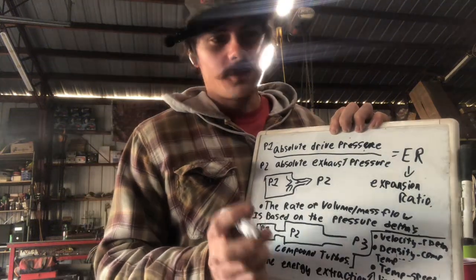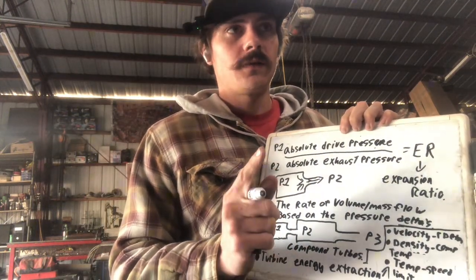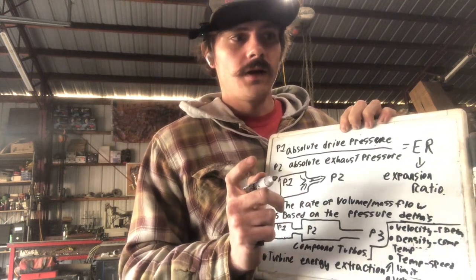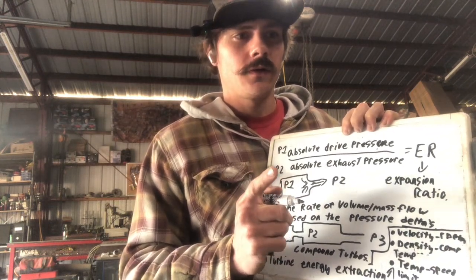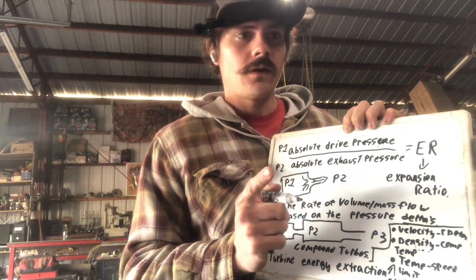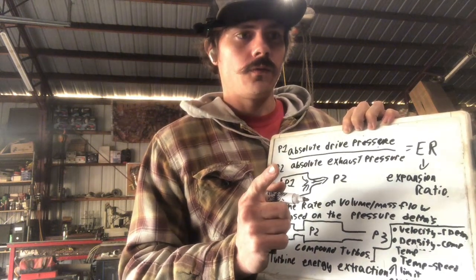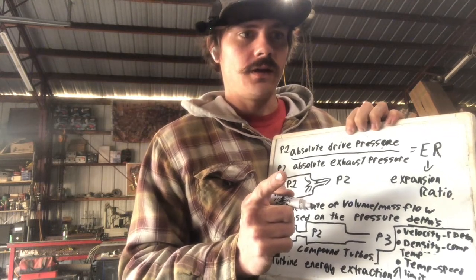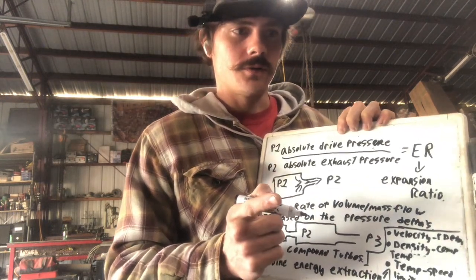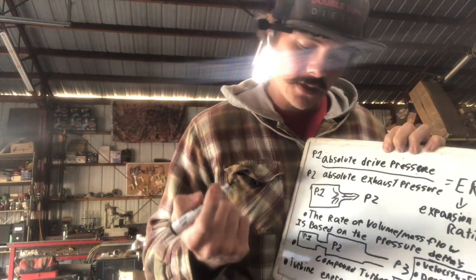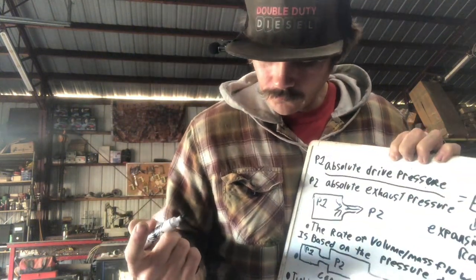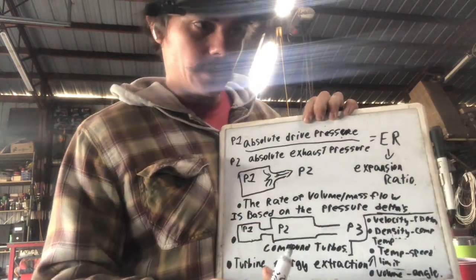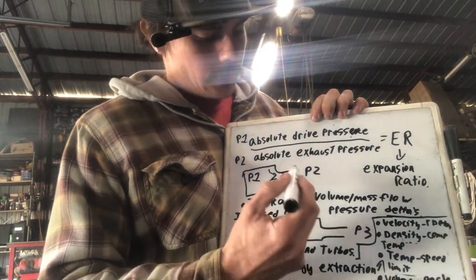This does not happen in turbocharging very often. VGTs, surprisingly, something I saw the other day, do this really well. Fixed geometry chargers seem to not do it nearly as well. They run into problems because the housing geometry to turbine wheel geometry versus gas speed, angle of attack, and all that jazz gets out of whack, and the thing gets mad before it even gets there. Which isn't a bad thing.